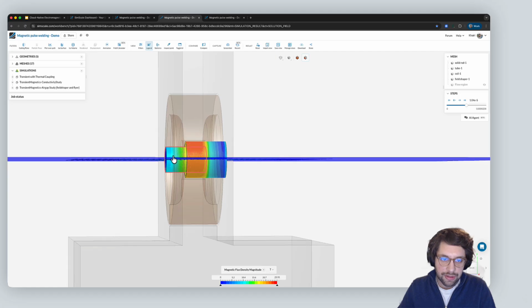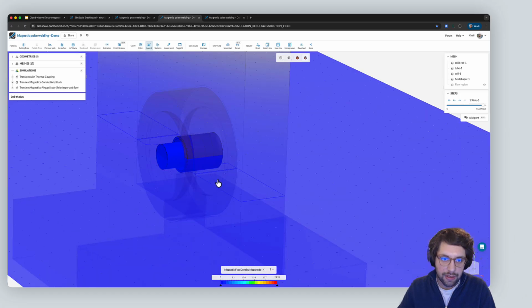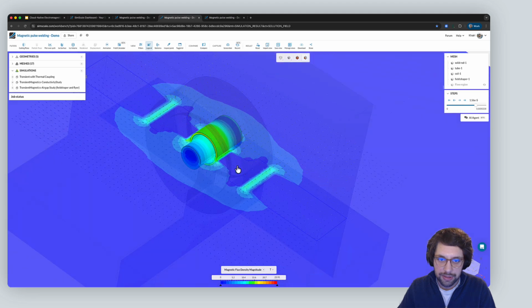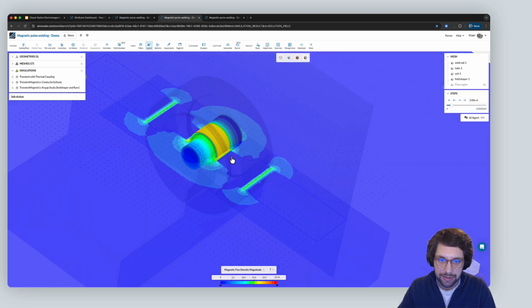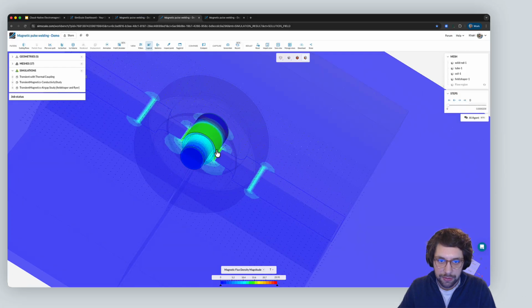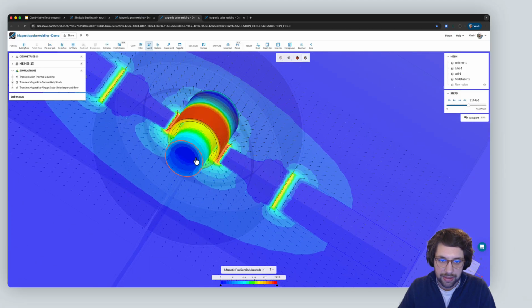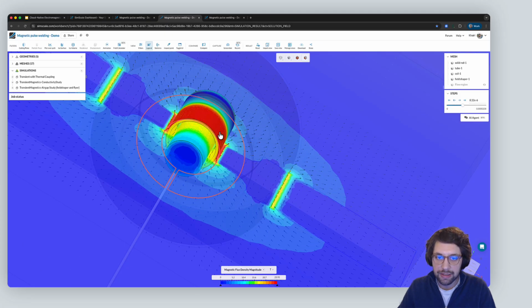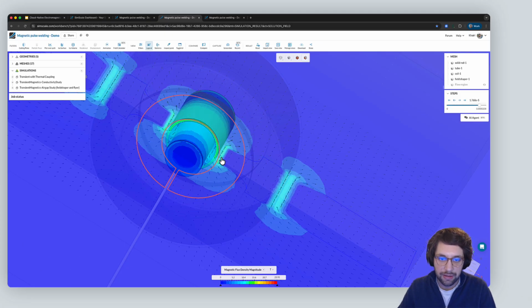What is very important is to make sure that the overall flux density within the air gap is right, based on the tooling requirements. For example, what is the overall air gap distance between the field shaper and the actual aluminum coil? That's also a very important parameter here that controls the overall amount of eddy currents that will be generated and consequently affects the forces.